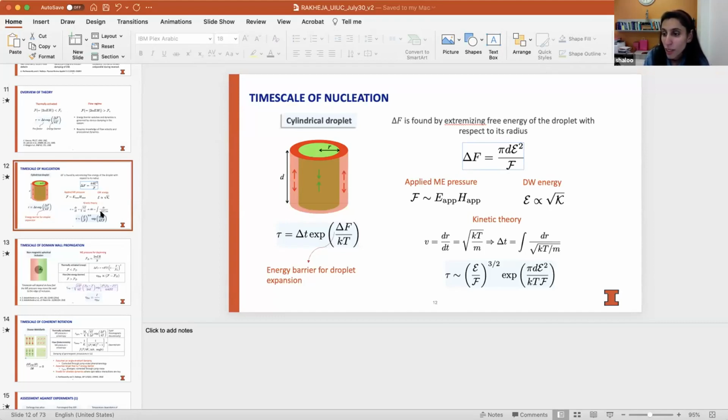What do you think about it? Well, I mean, there should be some thermal nucleation rate. You can have a reverse domain nucleus. It costs some energy, so it should occur in the Gibbs ensemble with some rates. Correct, but if you look at it this way, if it's a completely pure sample, then the formation of the wall is going to cost you a lot more energy. So it wouldn't happen. So it would happen at places where there are pre-existing defects or dislocations in the sample, correct? And so that's where we start.